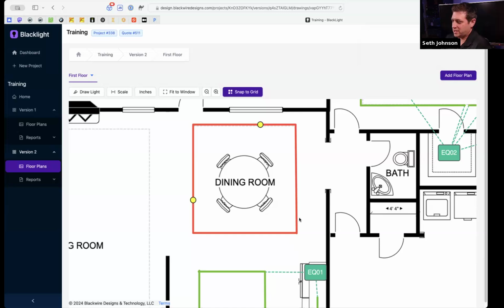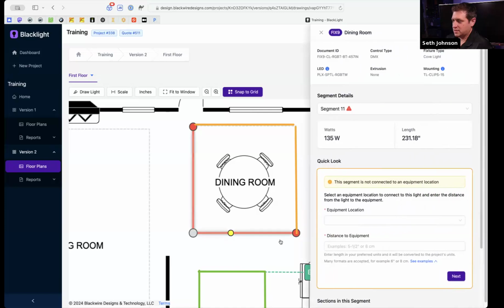There's no way you can really connect this entire length. We've gone over the max run twice for this, so we've got to split the segment up and repower it. But usually in these situations, you're going to go to the opposite corner and split it. So let's see what that does for us. Still have some max run issues because we've got this whole segment here. I see what it's doing. Interesting. So I'm just going to split it here. That'll be fine, and split here.